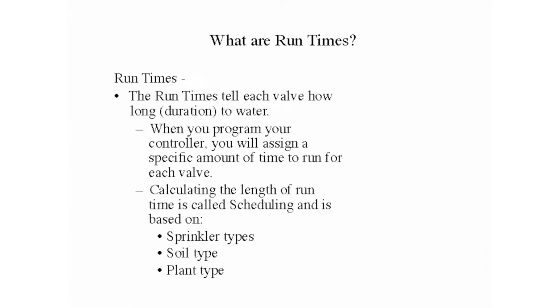Now, what are run times? That's really answering the question, how long do I need to run the system? So it's a specific amount of time to run each valve. Now, to calculate that is based on a term called scheduling. And I took 8 hours of scheduling. You can really get into details with scheduling. But basically, some of the factors that go into that is sprinkler type, because it talks about how much water is going down on the site.